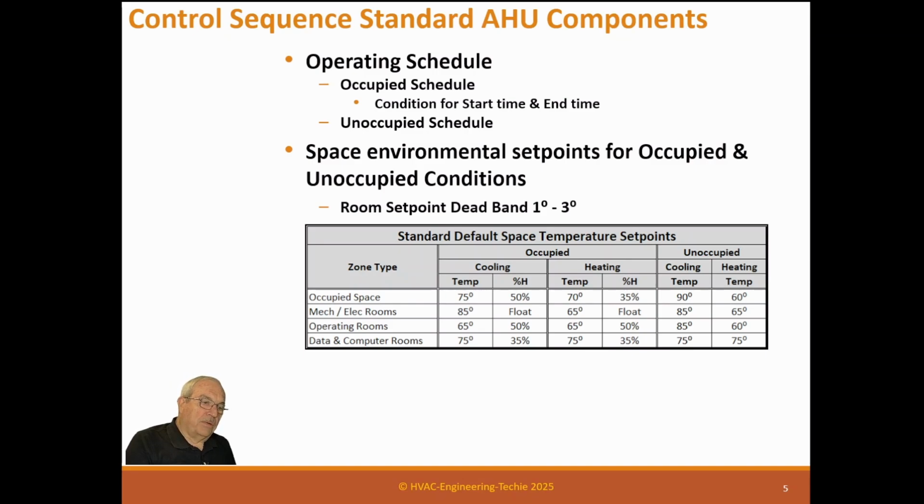And so we would pump 68 degree air into the space, so the rooms were always really cold for operators, trying to get that air to be below 75 when it gets across the chips. Well, now they're telling us that the new processors can do 95 degrees at the chip level, so we don't have to do 68 in the space. So we can do 75 degrees in the computer rooms and be just fine.